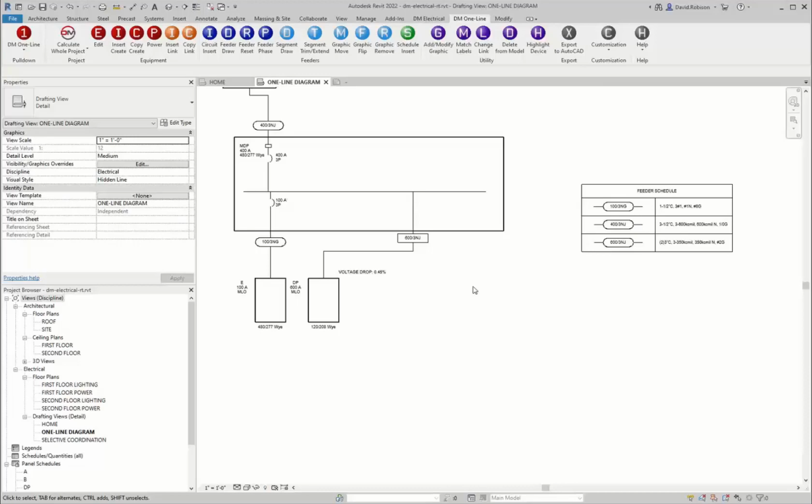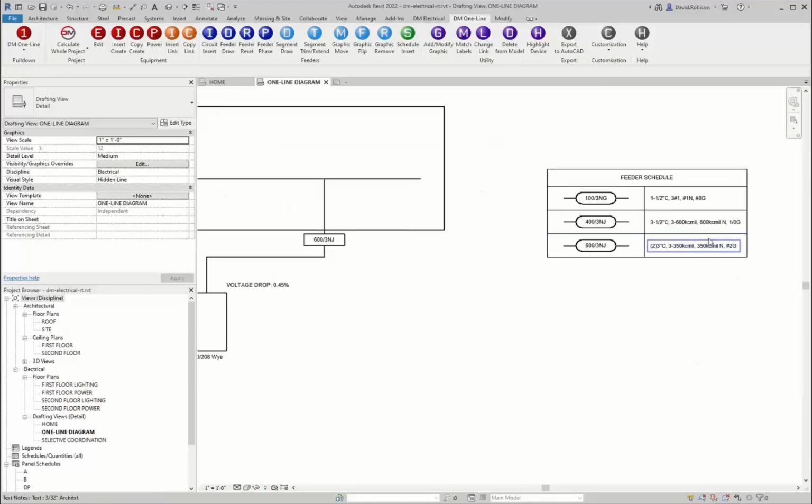Those are sometimes electrical equipment, sometimes electrical fixtures, sometimes other things. So you can't mash all that together in a single schedule. So we were not able to use Revit's scheduling feature to get it to work out. That's why we had to build our own little schedule drawing over here.